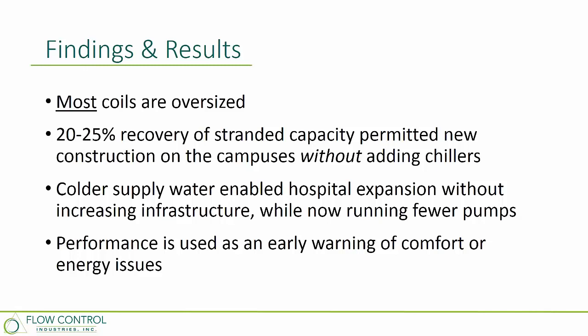And the reason they did that was that allowed them to get water further out into the system and actually serve more physical buildings because of the pumping limitations. So with that colder water, they were able to supply more of the campus. It did mean that they had to run more chillers and essentially all of their chillers to do that, but they had the capacity in the plant to do that.